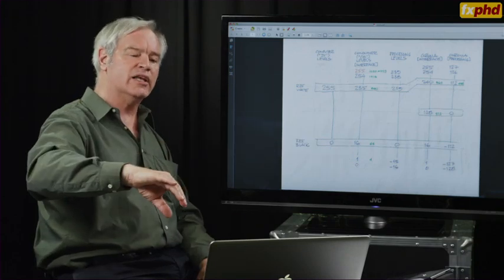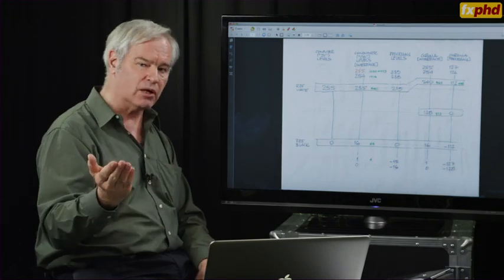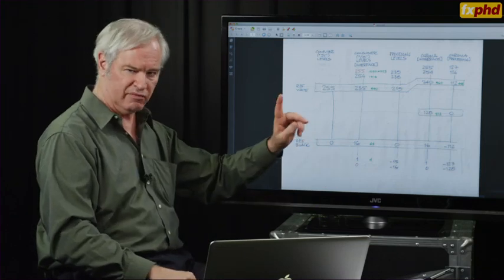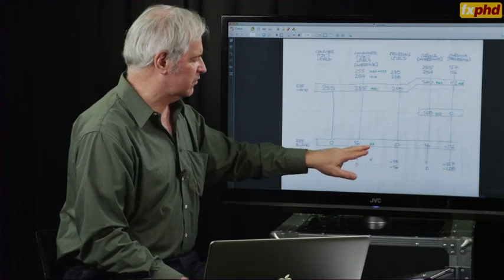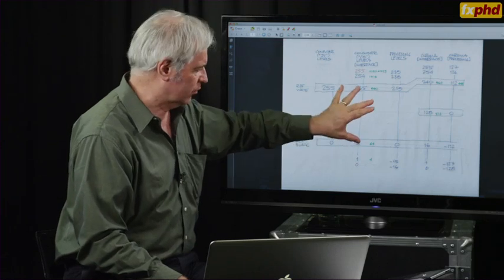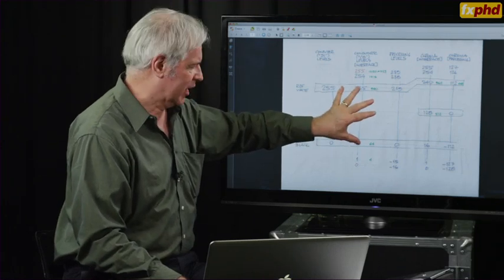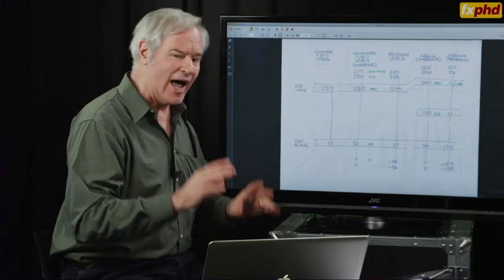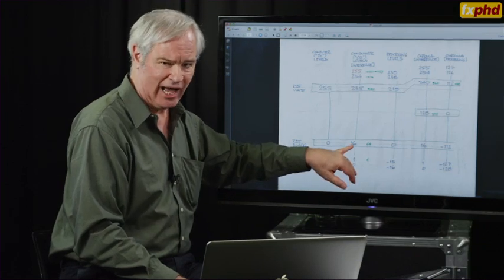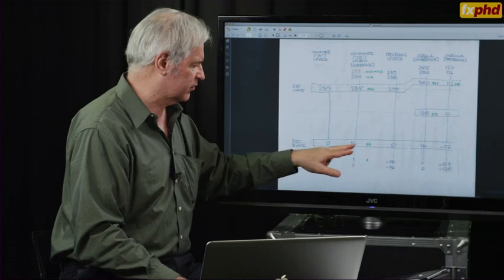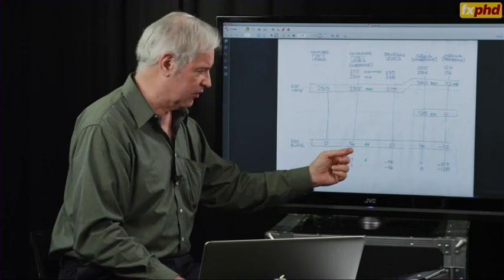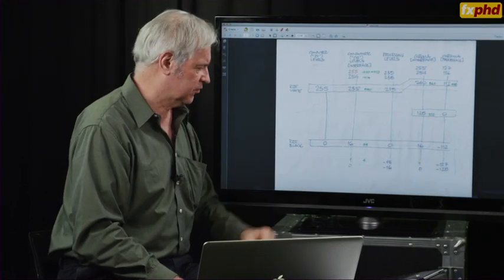Now, in studio video, for the last 20 years, we used 10 bits instead of 8 bits, simply multiplying those 2 numbers by 4. So you get 64 and 940 as the reference levels for black and white. Now, I hate how a non-zero number is used to represent black. And so my term for this number is the interface offset, plus 16, or in the case of a 10-bit interface, plus 64.